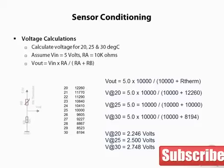Now this is something we can use in our process. We can measure it with our A to D inputs and linearize through code, tables, or equations, and then move on from there.